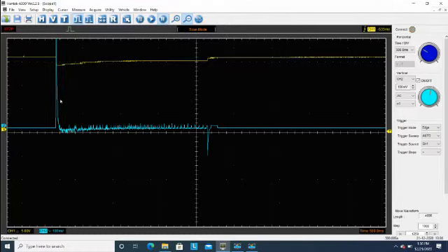Eventually this balances out, and you can see that our graph becomes very jagged on that blue line. The reason that graph is becoming jagged is we have to think about how an electric motor works. Inside this electric motor we have a commutator, which is a switching device. And it's switching current on and off to different parts of the electric motor as the brushes come into contact with that part of the commutator. And that's where those bumps come in. We can actually study an awful lot that's beyond the scope of this video about electric motors looking at these graphs, including actually calculating the speed of our electric motor.